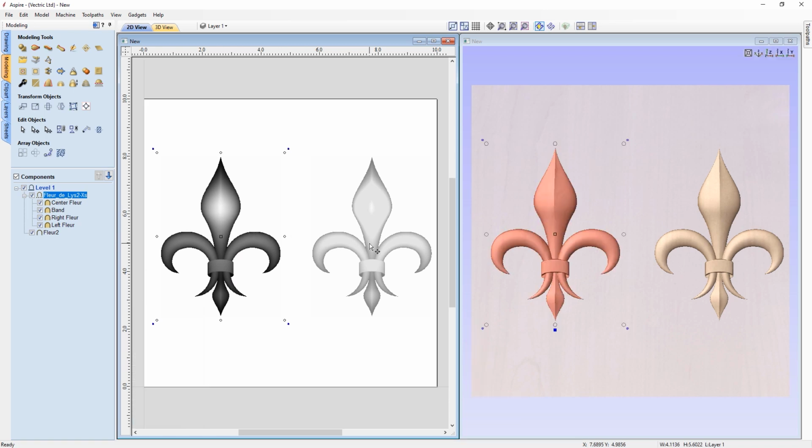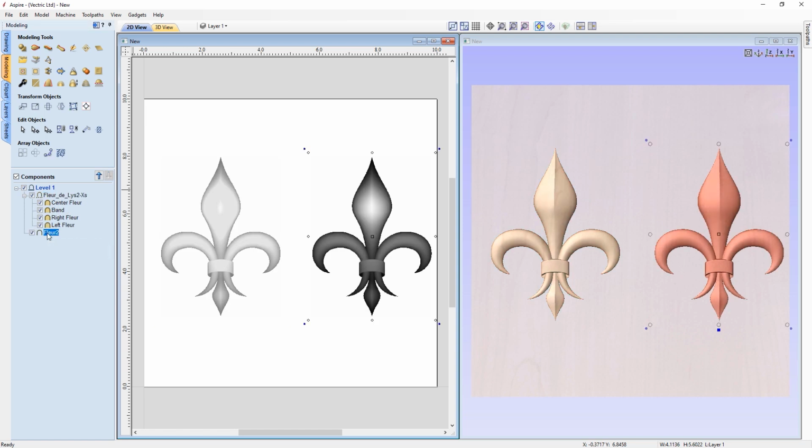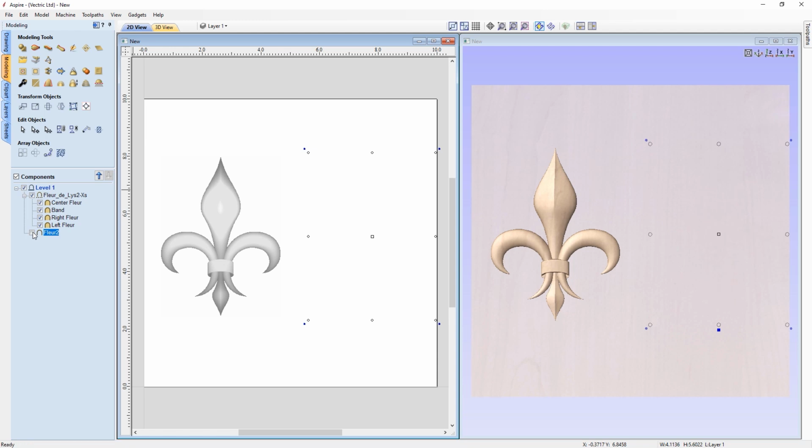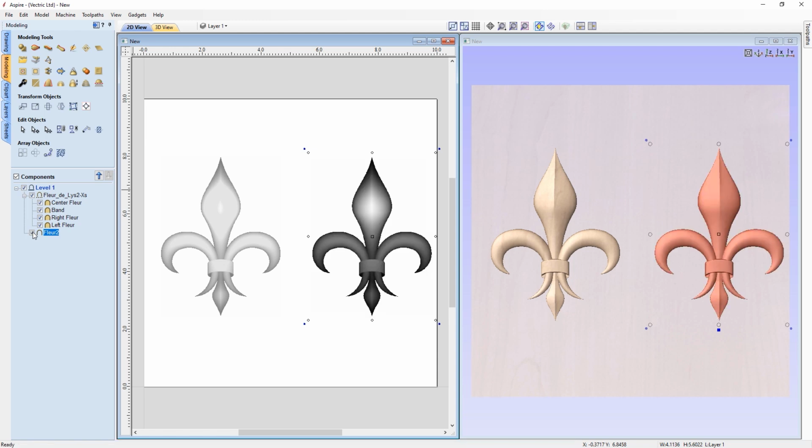As you can see, this is imported slightly differently. While they both look the same in the 3D panel, you can see in the modeling components list here, the 3D clip file has imported in as a group of separate components, whereas the original CRV3D file has imported as just a single solid component. If I hide this component, you can see the entire section disappears and reappears when I make it visible again. Whereas with the 3D clip file, I can hide smaller elements of this.